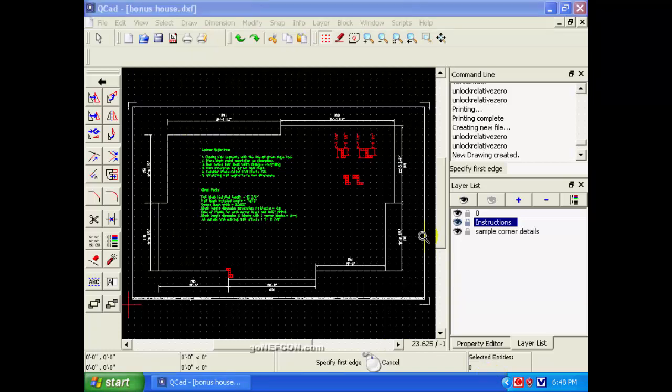An outcrop on a dry-stacked block home is where the wall moves out about 2 feet and then continues on. This makes the wall strong because we have the lateral force strength right here. The wall cannot be pushed in. So this L right here makes that whole full-length wall much stronger by anchoring the middle of it. So let's take a look up at these pictures for a moment.